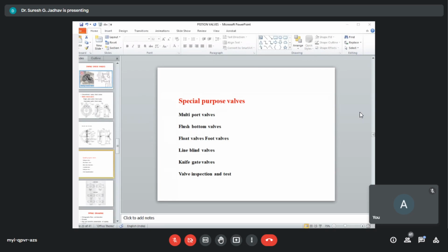These valves are covered under the Indian standard, IS 1703. There are two types: the first one is HP and the second one is LP, depending upon the pressure holding capacity of the valve. HP stands for high pressure and LP for low pressure. The body, lever, and internals are manufactured out of gunmetal, and the float is of PVC or copper depending upon the temperature of the fluid.